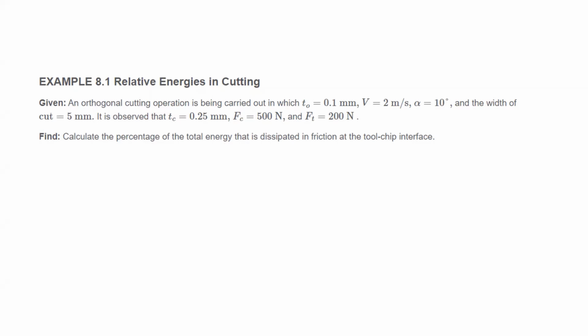And the total energy is the cutting force Fc multiplied by V. And this V is my cutting speed. I want you guys to draw down to do something. That's the reason I ask you to pull out a piece of paper, use some pencil or pen, and do some simple calculation. So, and this is a V and a Vc. Right? So V, we know that because the mass is conserved.